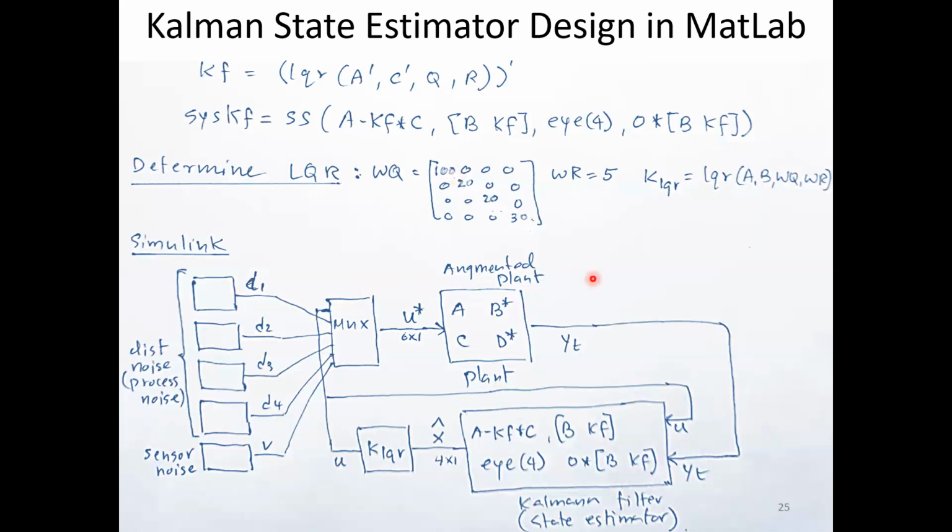Now with that, we can run this control system and see for ourselves what is happening. And also when you're running, you can change these values if you want, right? If you understand, okay, this is not correct. Control signal is very costly. To generate controls, you need to consume energy, right? Petrol, gasoline, or electricity, or whatever. So therefore, this has to be 100. And these signals can go up and down a little bit, doesn't matter too much. So you can reduce this 100 to about 50, right?